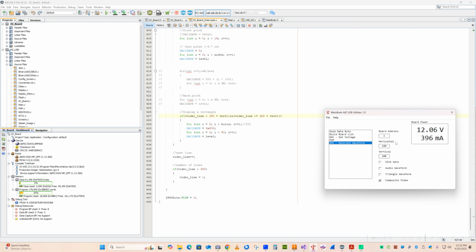So I could add a couple more boxes in here and send the data across, because I have it set right now where when you send information, it sends the whole 64 bits through the USB into the SRAM every time. So we can do lots of boxes. So you could actually change this level, make it global, and put a variable here for this. And you could change the height, the width, the position, the whiteness.